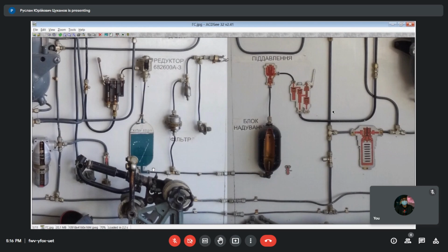So, each bottle at the inlet has a check valve. What for? Try to think a little. In case this pipeline is destroyed, this check valve will prevent immediate air release back to the atmosphere, and the bottles will keep some high pressure air to provide pressurization for some time. It's of course not for some hours, it's for some minutes, but maybe these minutes will allow the pilot to level the flight, to direct the airplane back, maybe to eject safely. So these minutes may be very important.